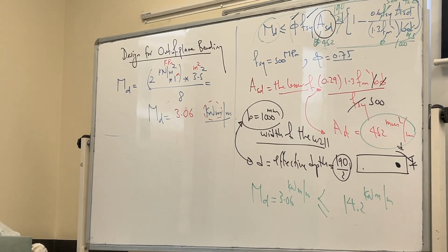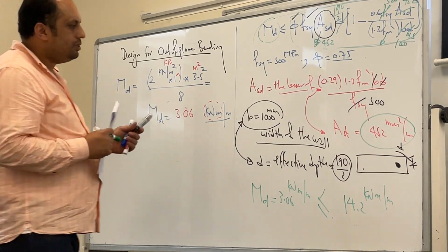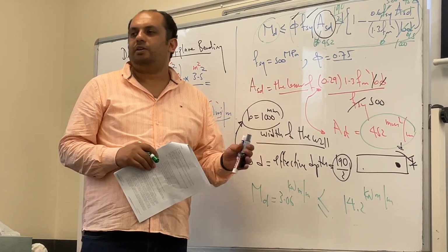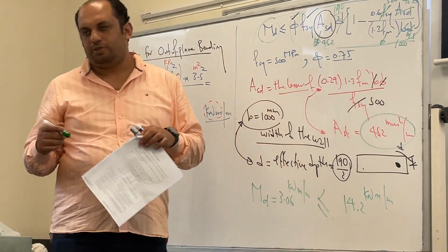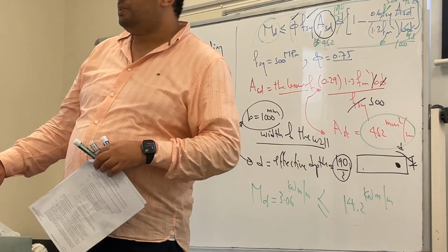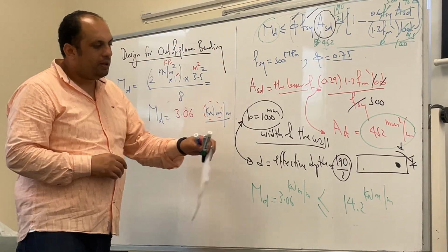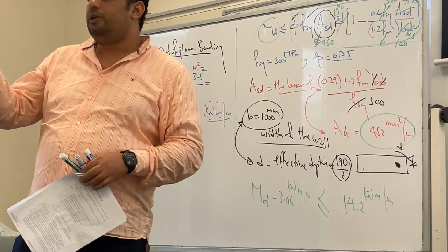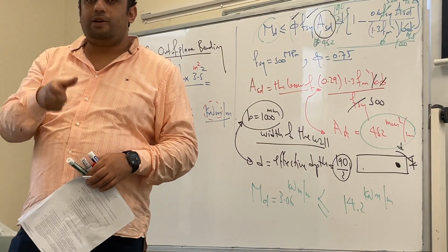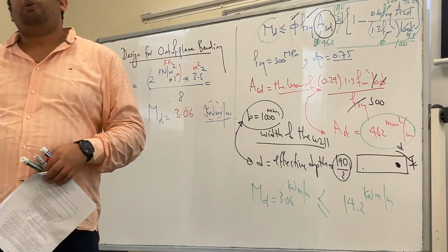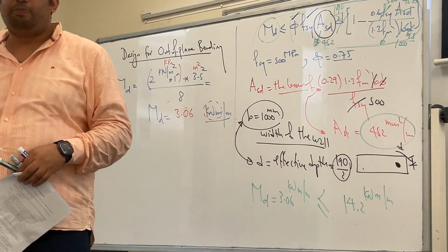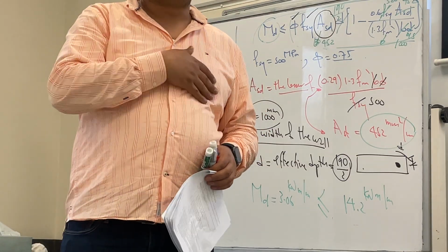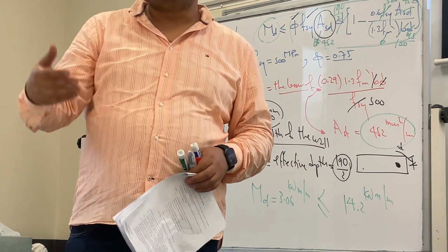Increase the bar. No, decrease the spacing. No, because we are already using the minimum, you have other options. One option is to increase the bar. Instead of putting one in every second hole, you can put one in each hole. Or increase the bar diameter, the size of the steel. Or increase the wall thickness. Or increase above the minimum, because we're already using the minimum only, right?